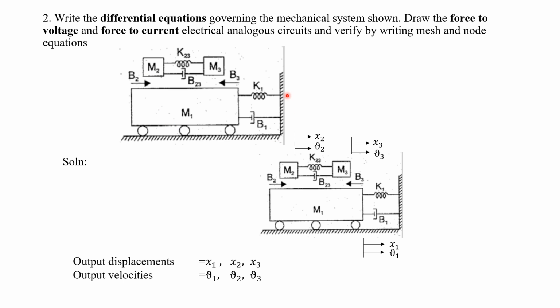The given system is a mechanical translational system because it uses the elements of mechanical translational system, that is M, B as well as K. In this question there is no input signal, that is linear force F. So no need to consider the input, only we have to consider the output for every reference element M1, M2 as well as M3. Here there are totally 3 masses.